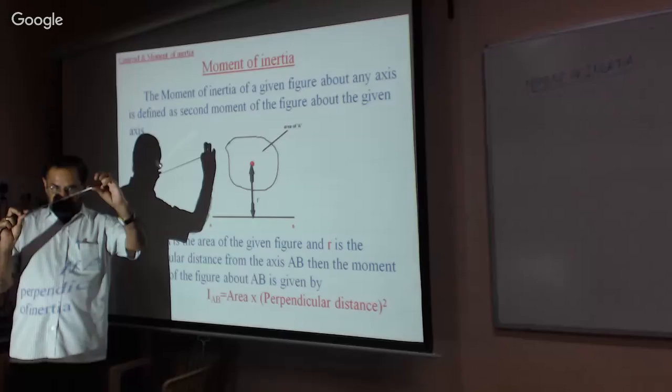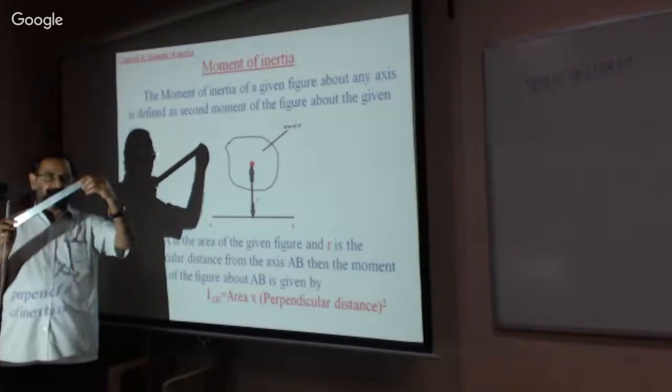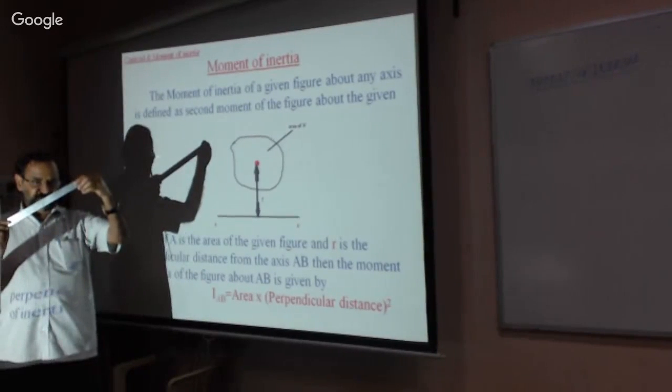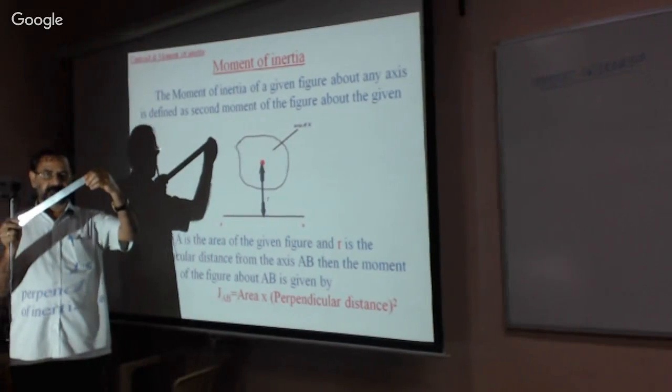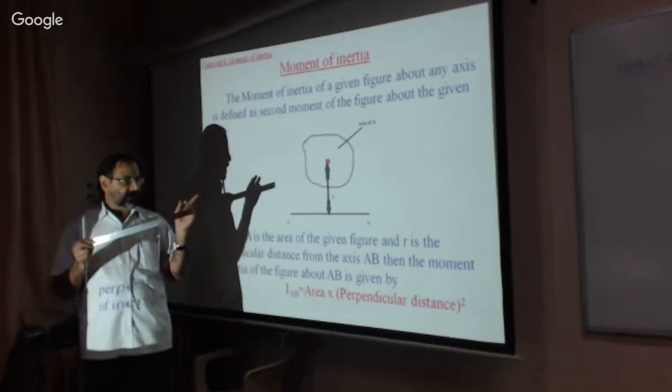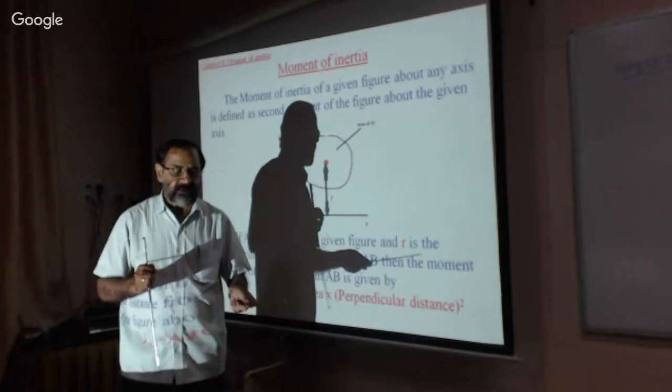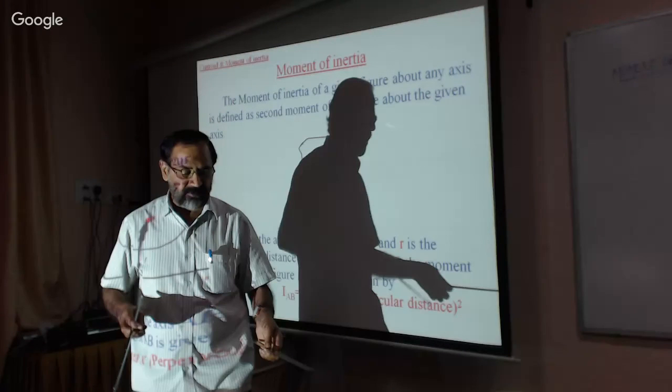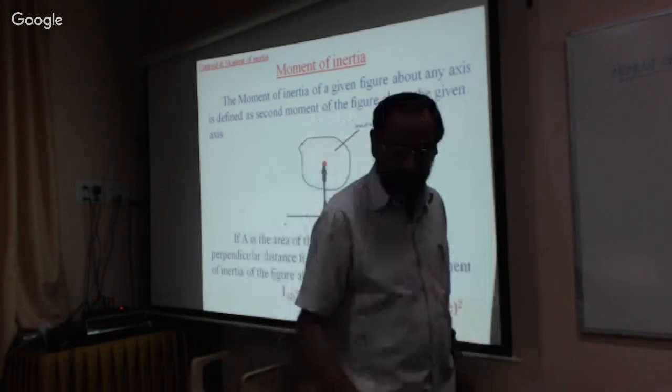They have placed it so because it resists more forces. The tile roof rafters are placed like this. The depth will be more and width will be less. This is just an example I have given you. Now we will discuss how to deal with this moment of inertia.